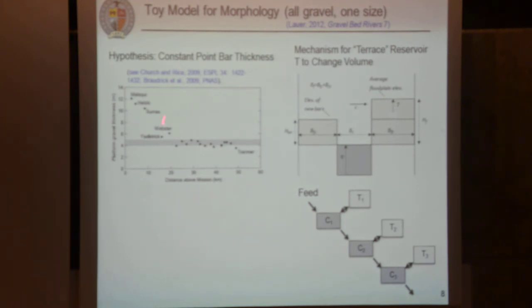And there's several papers out there that would indicate, on some systems or in some scale models, again citing Christian Broderick and some of his experiments, that typical meandering migration would produce a typical point bar height. Also on the Fraser River, typical bars are all roughly a constant distance above the thalweg. So that's the model here. We're assuming it moves out at a constant thickness, but it comes in at the average thickness of the gravel deposit, which may be more or less than the gravel bar thickness.